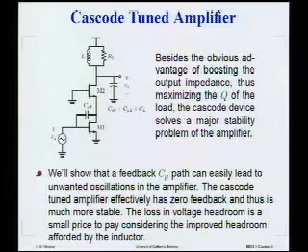Alright, so now we can also make some variations on this tuned amplifier. For instance, we can do a cascode tuned amplifier. Again, cascode amplifier is really nice because effectively a cascode stage just looks like a normal transconductance stage. Has the same input impedance, but it has higher output impedance. Here that's a help because the higher output impedance means that we load the tank less.